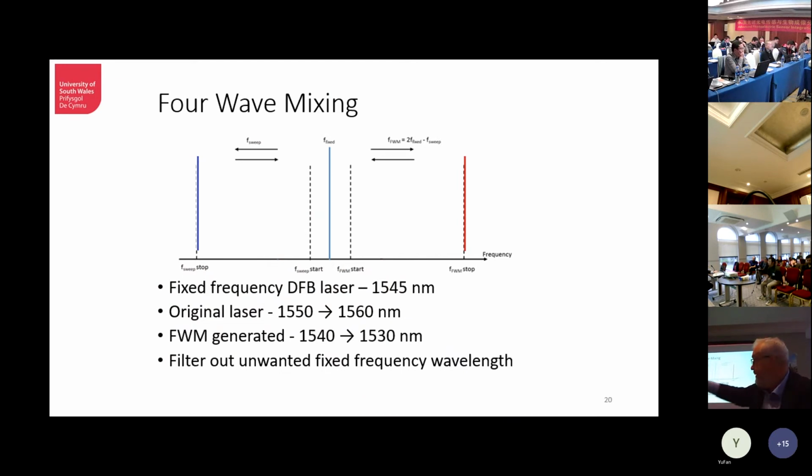When we were in Silicon Valley, when you go down the optical fiber, you've got channel spaces of 50 gigahertz. Well, at 50 gigahertz, you might have, say, 20 gigabits of data on each channel. But what you found is when they made the dispersion of the fiber 0, because that was the drive in the late 90s, get the dispersion to 0, we'll maintain the quality of the signal. But when they did that, alongside equal channel spacing, what they found was, because of 0 dispersion, they were getting crossed up between the channels through a phenomenon called 4-wave mixing.